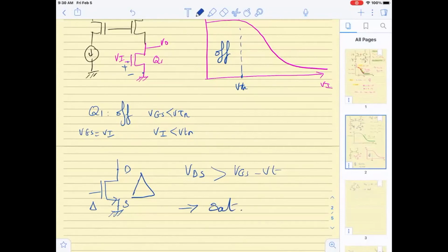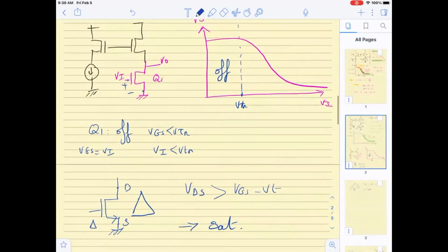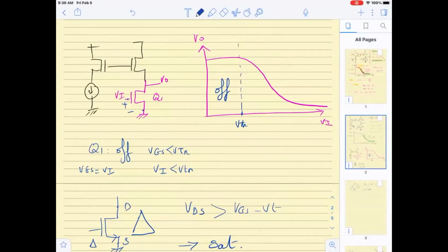Saturation. So the intuition tells me that when the output is initially high and Vn has just turned on, just exceeded VTN, the chances are it agrees with the fact that the device is in the saturation region. So for the input beyond VTN, I start in sat.